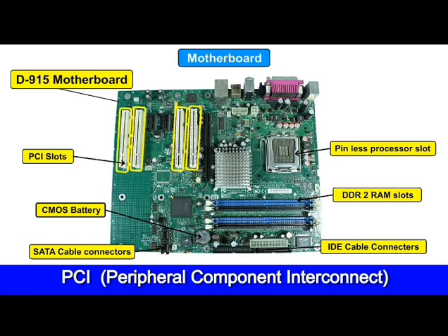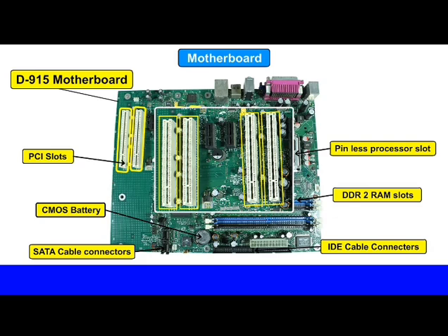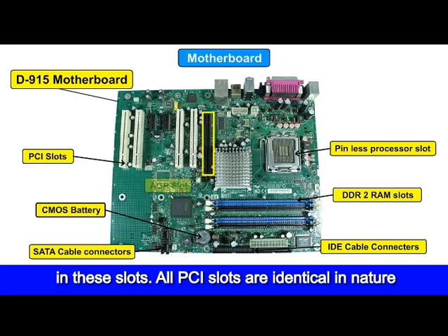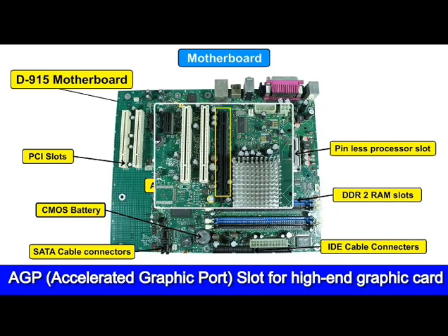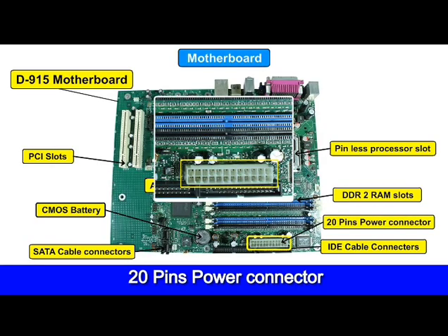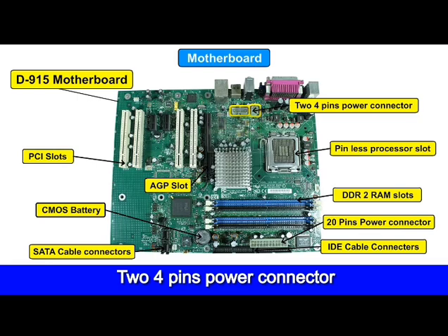PCI, Peripheral Component Interconnect, slots to expand the capacity of computer by connecting add-on card in these slots. All PCI slots are identical in nature. AGP, Accelerated Graphic Port, slot for high-end graphic card, 20 pins power connector, two 4 pins power connector,